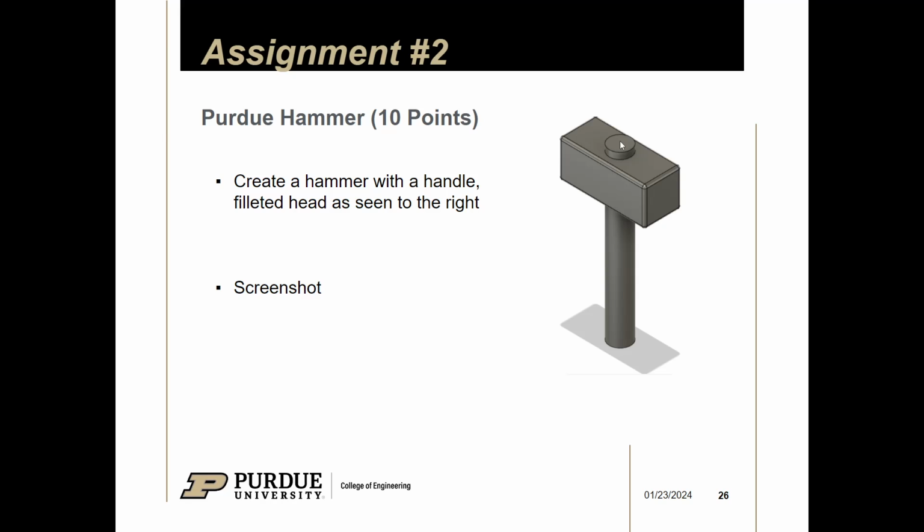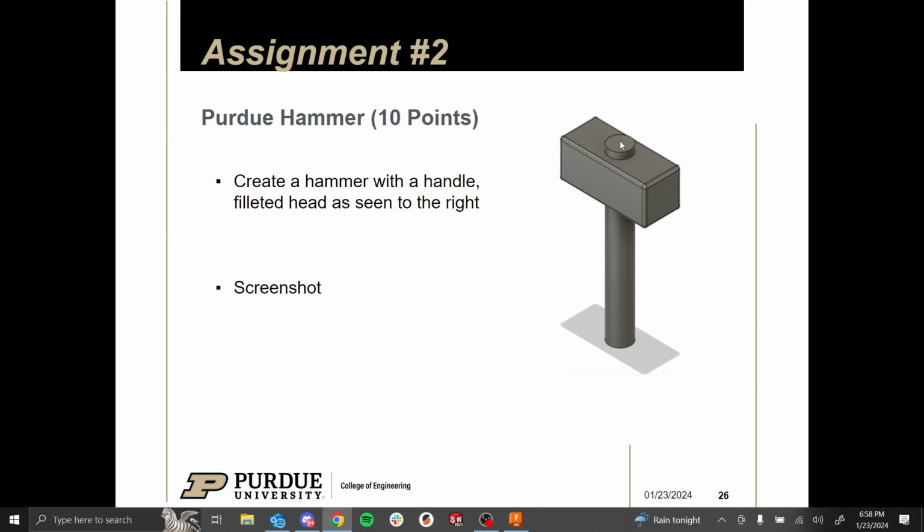There's multiple ways you could go about doing this, right? You could make the rectangular prism extrude upwards out of the cylinder, and then make another extrusion on top of it with a smaller cylinder. But in my case, I want to be more efficient and use fewer operations to get that part I want. So I'm going to use an offset from the sketch to create the extrusion, right?